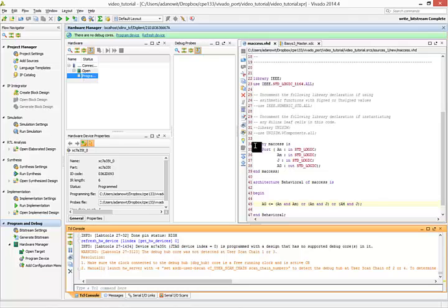So on something like this, where there are only a few test cases, it's generally a good idea to run through all of them to make sure that all test cases work the way you expect on the board. If that is the case, then your circuit is programmed correctly, your circuit works correctly, and you're done. Congratulations, you've just learned how to program your first design on a Basys board.